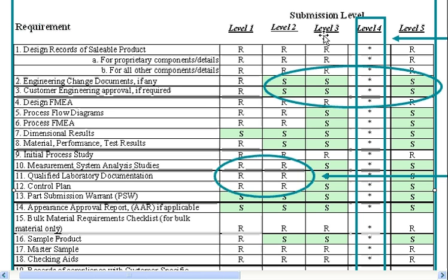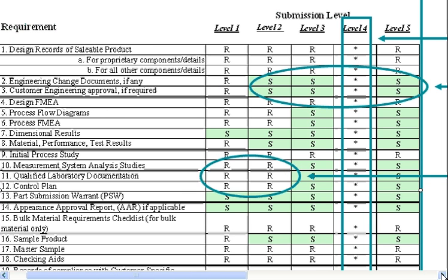So if the customer requires level 3, normally we will include the engineering time in the tooling charge. If the customer requires the PPAP level 3 after the sample is submitted, which we didn't include in the original quotation, we should propose an engineering charge to the customer, and most customers will understand that, because that's a lot of engineering work.